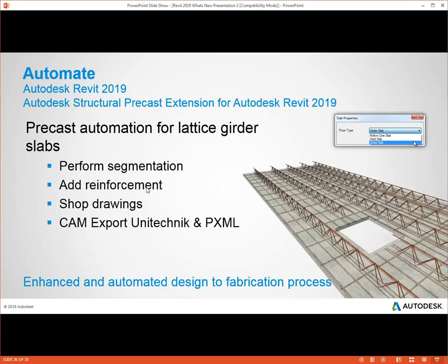You can add reinforcement based on predefined rules to automate the process of modeling the girder assemblies. You can also use this feature in conjunction with shop drawings. It now includes CAM export features, meaning that going from your design to fabrication has been simplified. So again, it helps to enhance and automate the process of design to fabrication.